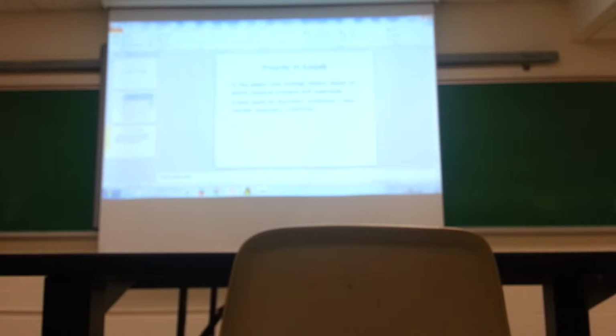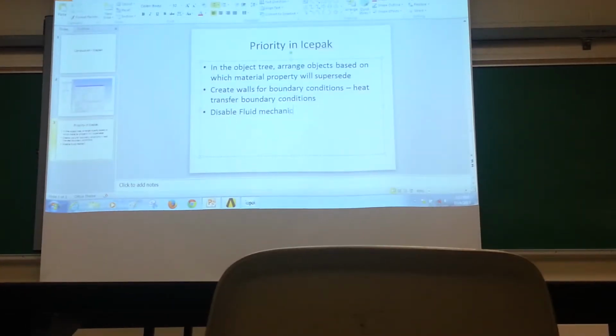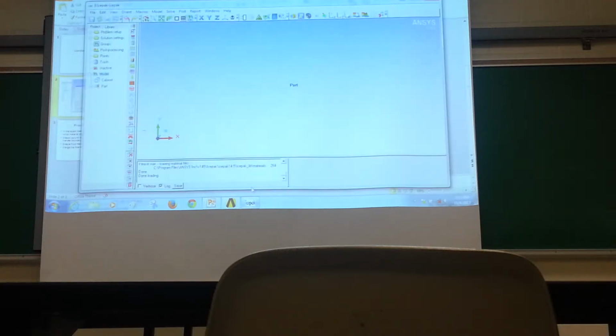We also need to, first of all, disable fluid mechanics, and change the tolerance. Okay, so it's just a couple of things you have to do, and then there's one other thing. Let's do all this stuff first.